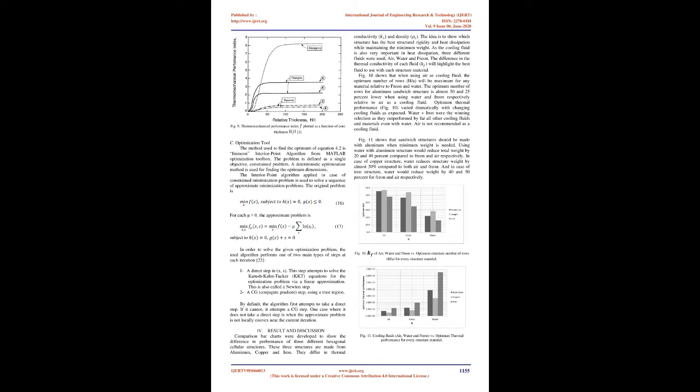Following reference 3, they have introduced a dimensionless thermomechanical index, equation 13. The ratio of total heat transfer rate to the pumping power needed to force the fluid through will affect the heat transfer performance of a heat sink. The higher this ratio, the better the heat sink performance. This ratio is then multiplied by the in-plane shear stiffness, as it is used for an indicative measure of the structural utility. The objective function is defined by these two steps.